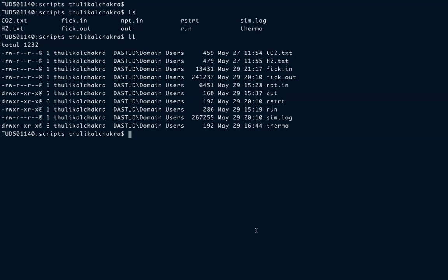To enable the calculation of these cross correlations, I'm using the OCTP module, or on the fly calculation of transport properties module, developed by the engineering thermodynamics group here at TU Delft. Thus, one has to first install this module into the LAMMPS source files, which should then be compiled to give you a new LMP serial file. Let us first do this.